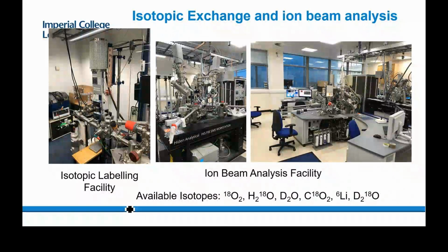And this is our newer instrument, the Hi-5 SIMS instrument, which will allow us to do simultaneous negative and positive species. So we can measure both ionic types at the same time from the same spot and get down to resolutions of 30 nanometers. You can then start to interpret grain boundaries. Do you have preferential diffusion pathways? Rather than just having bulk diffusion, does it preferentially sit on the grain boundary, or are the grain boundaries blocked? Do you have contaminants, etc.?